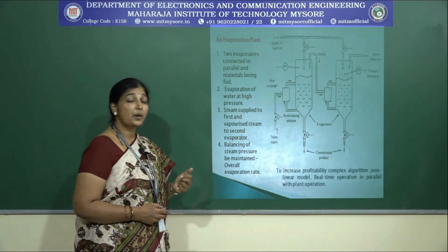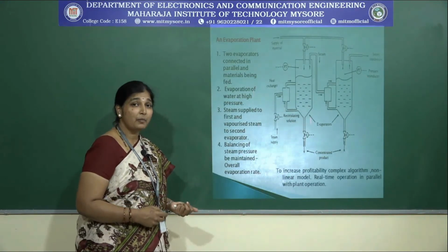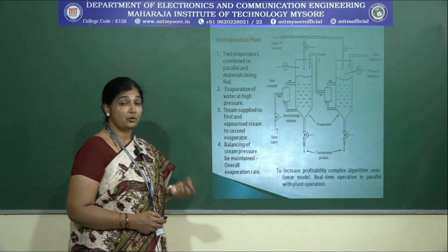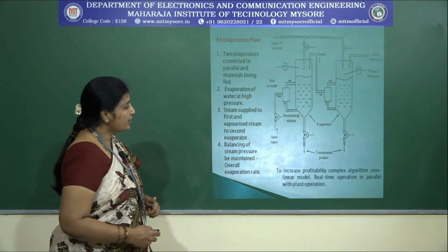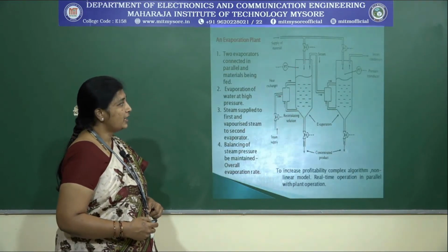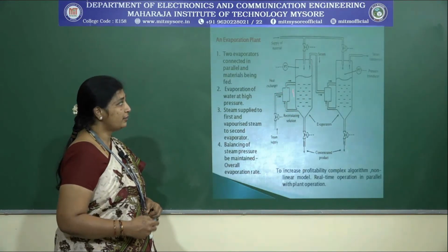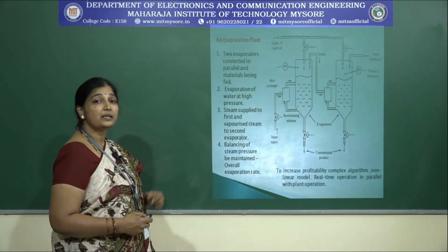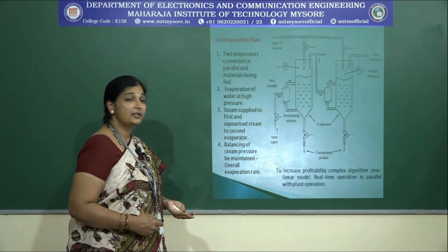Now what is supervisory, who should supervise what? In this kind of plant, pressure plays a critical variable which needs to be supervised. If you are letting steam supply into the first chamber, a sufficient amount of steam is fed in and a high amount of pressure is exerted so that evaporation happens to a greater extent in the first chamber.